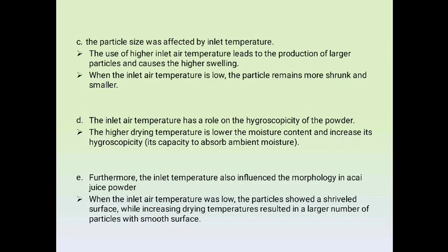The inlet temperature can also affect the particle size. The use of higher inlet air temperature leads to the production of larger particles and causes higher swelling. When the inlet air temperature is low, the particles remain more shrunken and smaller. The inlet air temperature also has a role in the hygroscopicity of the powder. A higher drying temperature lowers the moisture content and increases its hygroscopicity, its capacity to absorb ambient moisture.